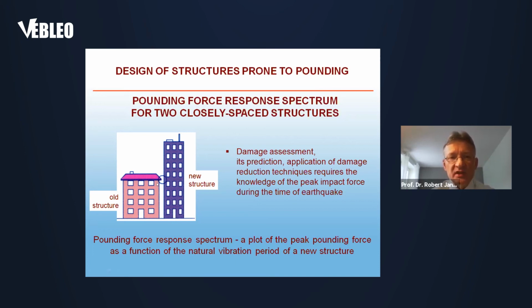Imagine that we already have one old structure constructed, and we are going to build a new one close to it. What kind of parameters should we apply, what natural period should the structure have, how much can we go to the left or to the right side, and of course how large the gap size should be, so as to minimize the effects of pounding.